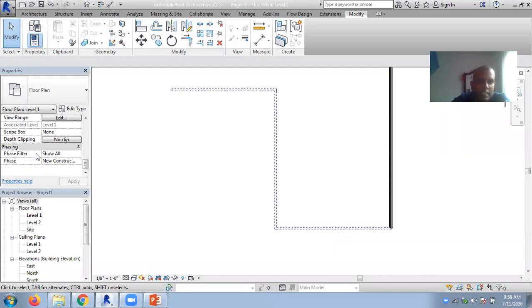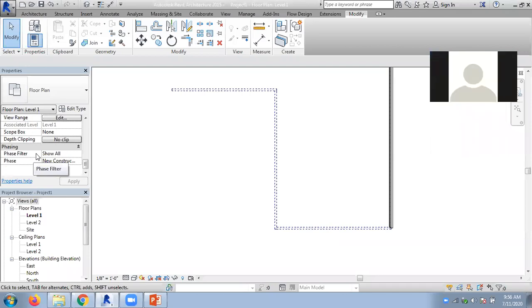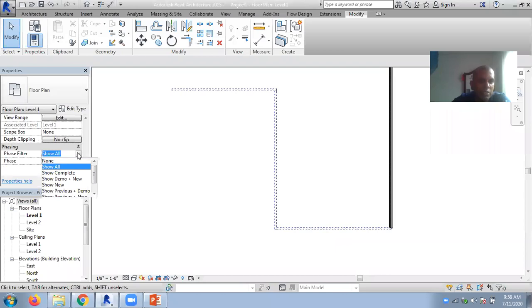You can have phases in your designs, like the initial phases, construction phases, likewise. You can have your design divided into phases, and now here I have only two. You can have a lot of phases like foundation phase, wall phase, roof phase, floor phase. Likewise, divide the project into phases and get quantities in different phases, and we can have a demolished phase here and put our demolished drawings in the demolished phase.